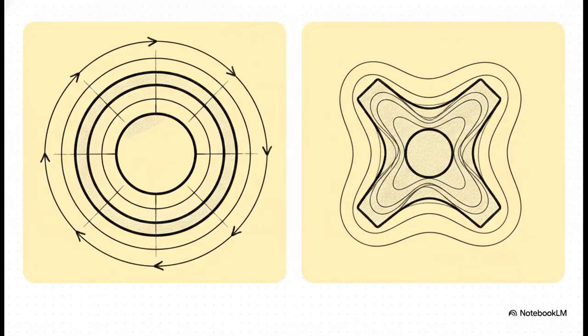Okay, so why does this happen? Well, it actually starts with the physical geometry of the machine itself. Think about our 2 main types of rotors. Cylindrical rotor generators, these are the ones usually driven by high-speed steam or gas turbines. They have a perfectly smooth, uniform air gap. Because of that beautiful symmetry, their magnetic reluctance is uniform, meaning their reactance is exactly the same in every direction. We say their direct axis reactance, XD, equals their quadrature axis reactance, XQ.